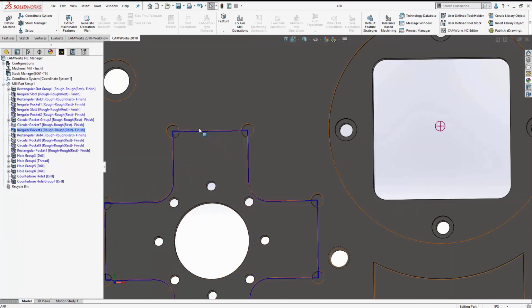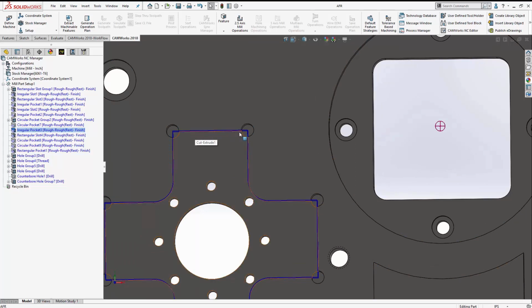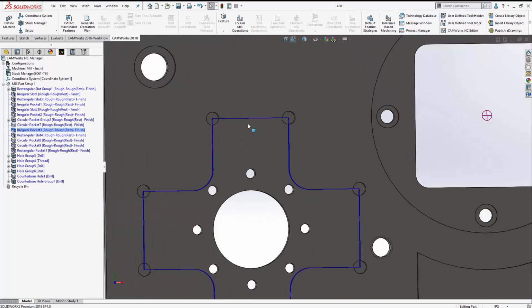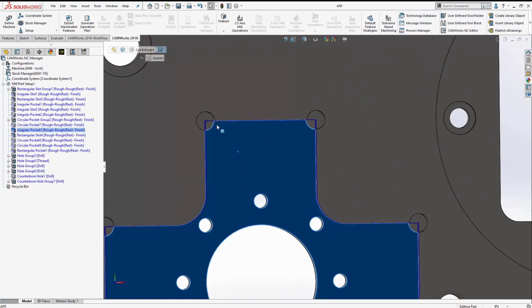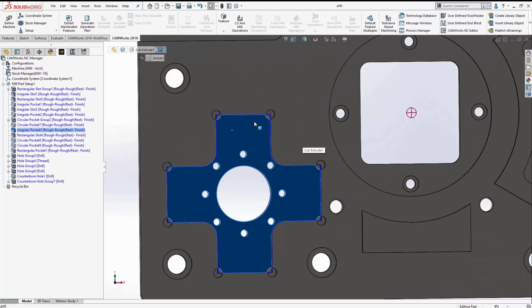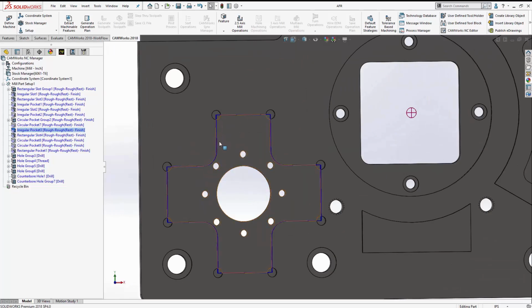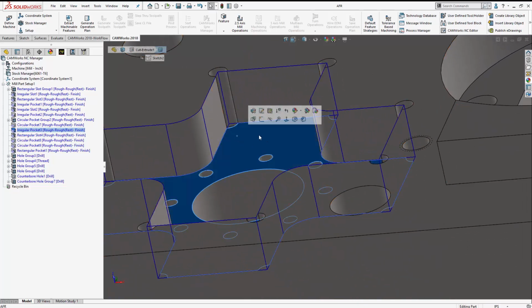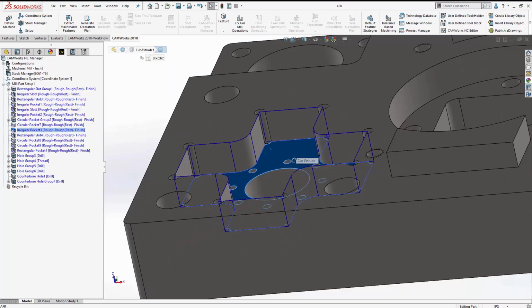As we can see, the toolpath is showing that it's going into these holes and around. Now, if I don't have simplify features on, it's going to use this highlighted profile. It's not going to go into the holes, it's just going to stay on the outside. So simplify features really tries to give us rounded geometry. It can overlap some features that are at a lower depth. So the floor must be lower than the floor that it's actually looking at.